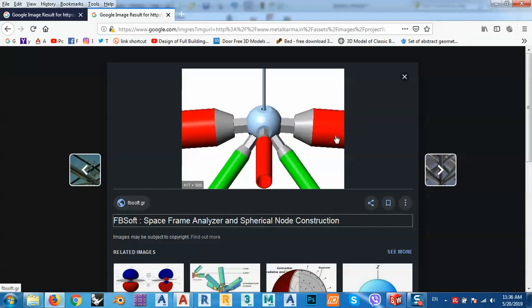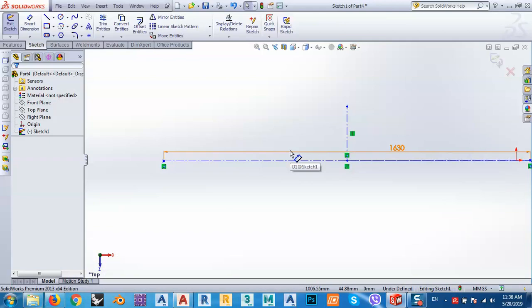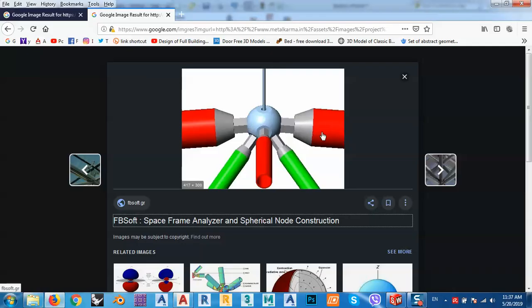In SolidWorks we can make these types of shapes as solids with a revolution, like in any other 3D program. And don't forget that this length is from node to node, which is the point of intersection of the lines, and this is the distance between those points. So what I have to do is decrease the nodal diameter of the ball, like this. This is the center, till the middle, the center of this ball. So I have to subtract this ball diameter or ball radius from it.